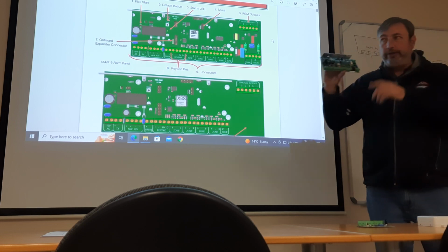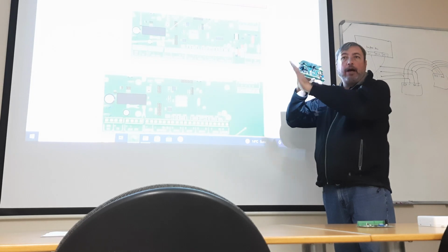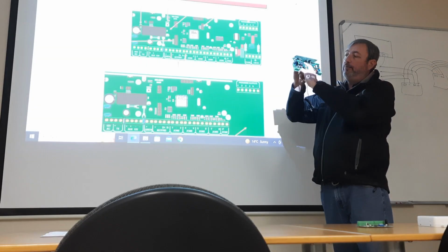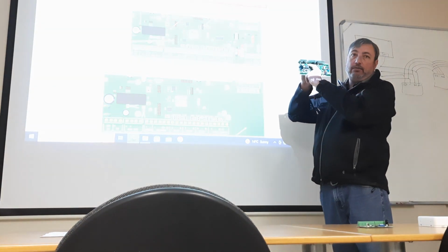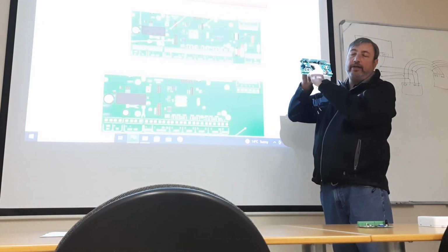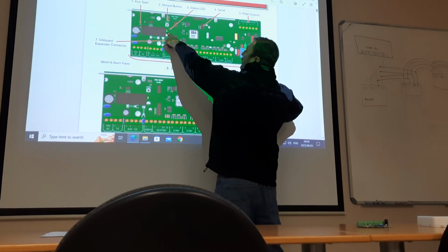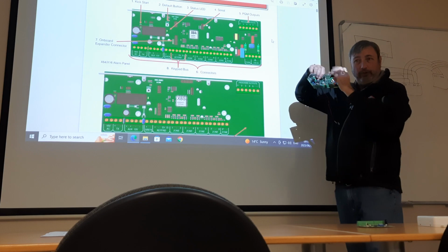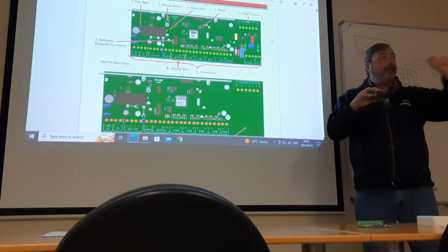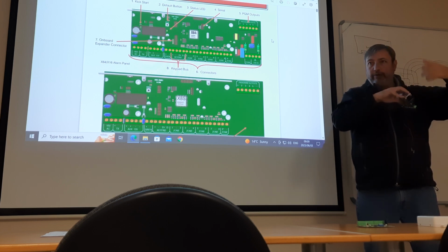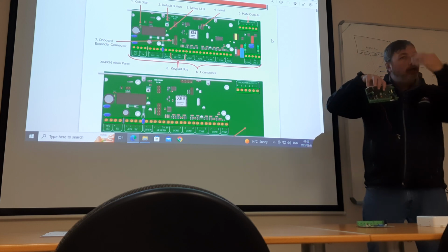Then what you do is, you switch off the power, plug the batteries out as well, so there's no power on the unit. Then you press that button in, keep it pressed in, you switch on the power back, and you keep it in for about 20 seconds. You'll see there's a status LED just below the button. After 20 seconds or so, it will start flashing. Then you release the button, and you will see on your keypads it says unregistered, unregistered, unregistered. It will reboot, and then everything that you programmed on it will be wiped out. And you can go and reprogram it again.